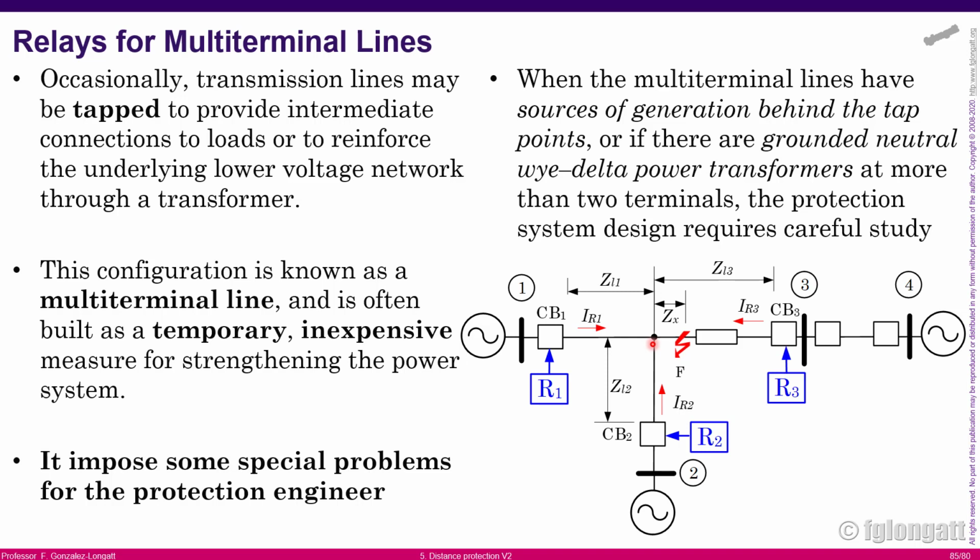What is tapping the line? We have a full transmission line and we connect in the middle of the field. Probably in one tower, we make the connection between one transmission line and the other, creating that T that we can see here. I don't know if you realize, but over there, there are no circuit breakers because that is not a substation. That connection is happening in the middle of the field. We have a tower, we arrive with another tower, we connect the wires together, we make that node over there. Some books use the letter S for that node.